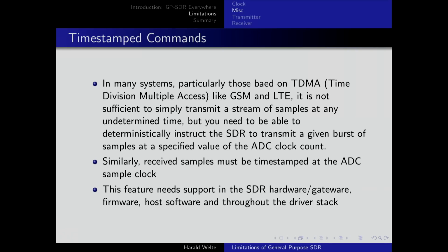If you receive signals, it's very important to know the precise time at which a certain sample, or the first sample of a block of samples, has been received, because that is important information. For example, in GSM and LTE, that information determines, among other things, from which phone that is actually transmitted, because there is time division multiple access happening. So it's important to have this functionality.